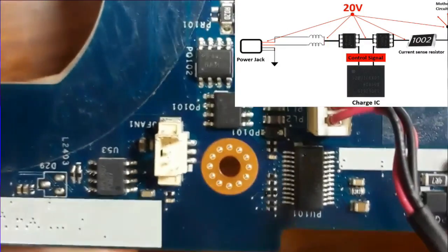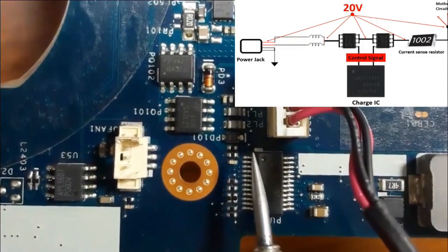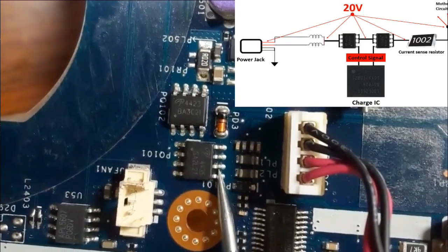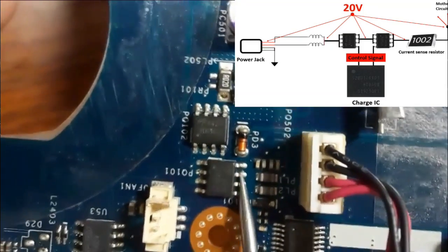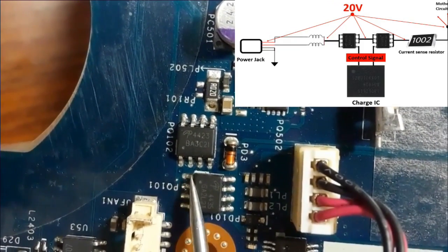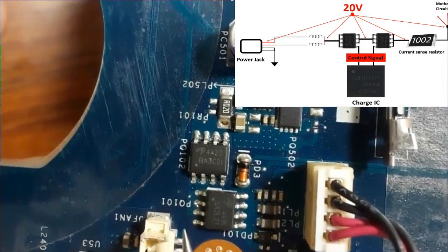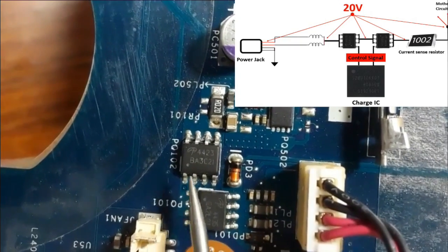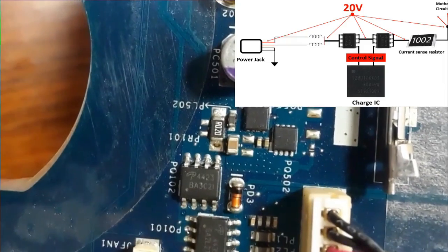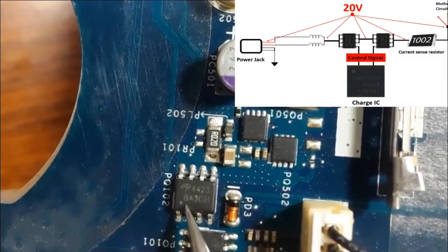So as you can see, this is the failed MOSFET. Here, these are inductors, as you can see. We get voltage here, and also we get voltage here in the drain of this MOSFET. Here we have the source. We have this dot here, which means this is the first pin. These three are source. Here we have the gate. For this MOSFET we get voltage here, and we get the control signal, but the voltage doesn't pass to the drain, to this side. So this MOSFET is a bad MOSFET.